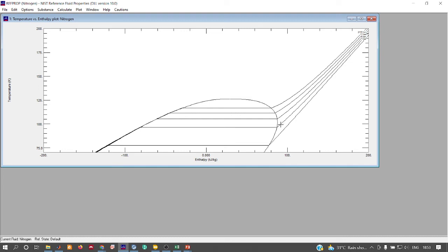So when you are expanding from the saturated vapor region, whatever liquid product you are getting is just zero. So that's how there is a sudden jump. Since we are talking of a pure component, at every pressure you have a fixed temperature, the saturation temperature. If you expand it below that temperature, you'll have more liquid. So that's what we could see over here.